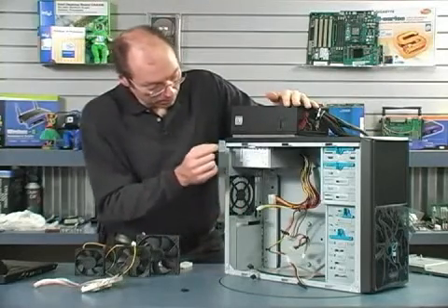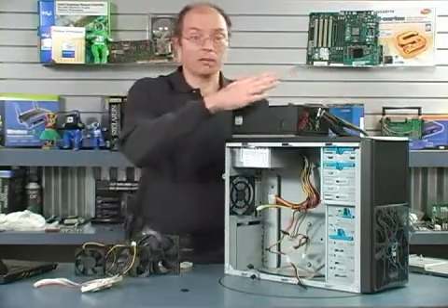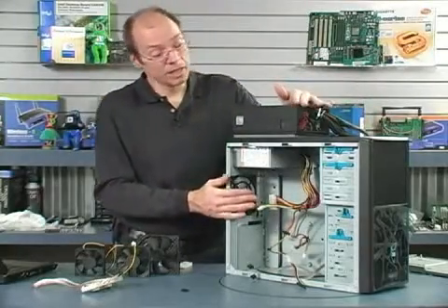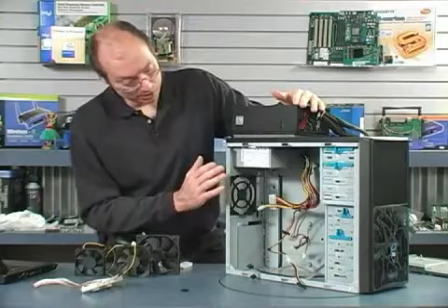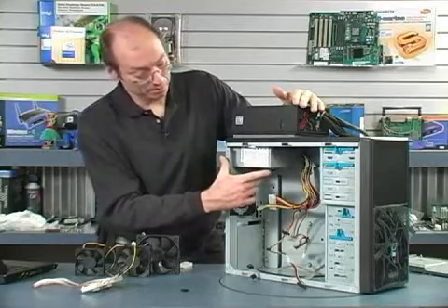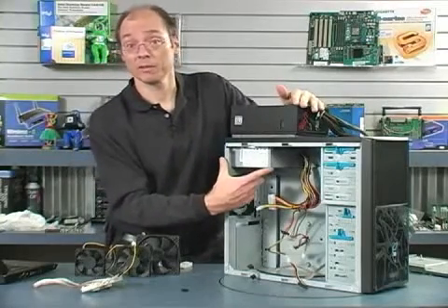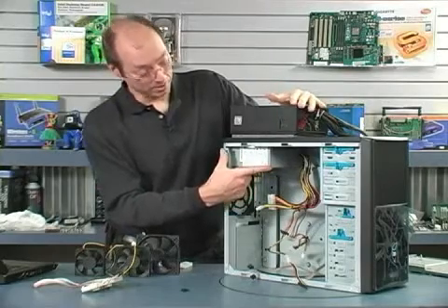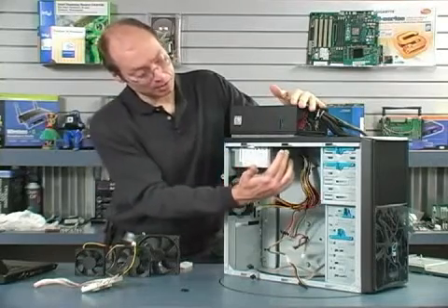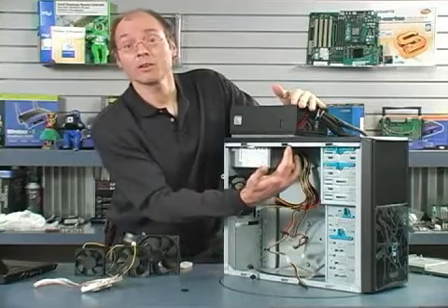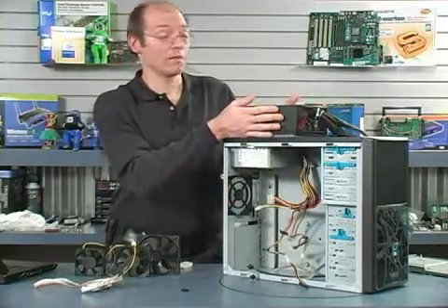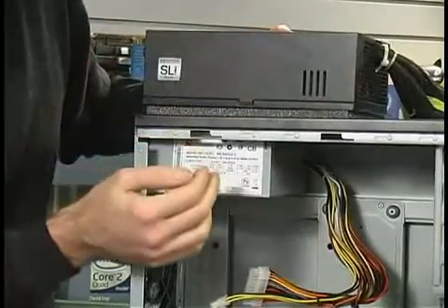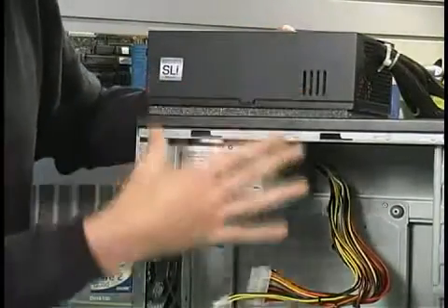So we want to make sure we have, as I said, the adequate power to power the motherboard, video card, all of the drives in the system. Now, one point about power supplies. The ATX standard calls for a power supply that's 140 millimeters deep. But there is an auxiliary to that standard that allows the power supply to go as deep as 180 or more millimeters. And this is an example of the deepest type of power supply. These are called EPS power supplies. And as you can see, this power supply would actually fit in this case.